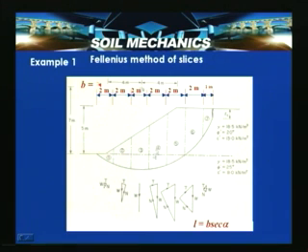Similarly, weight 4 is considered by using this particular procedure. Here it so happened that gamma is the same for both the soils, which is given here. This vertical distance is 7 meters for the center of rotation, and 5 meters is the height of the slope. When we plot this T and W, W is the weight of the slice. The force diagrams are shown here.